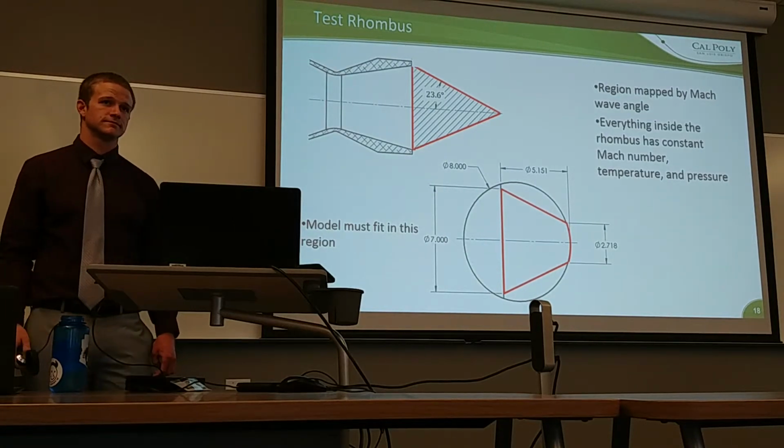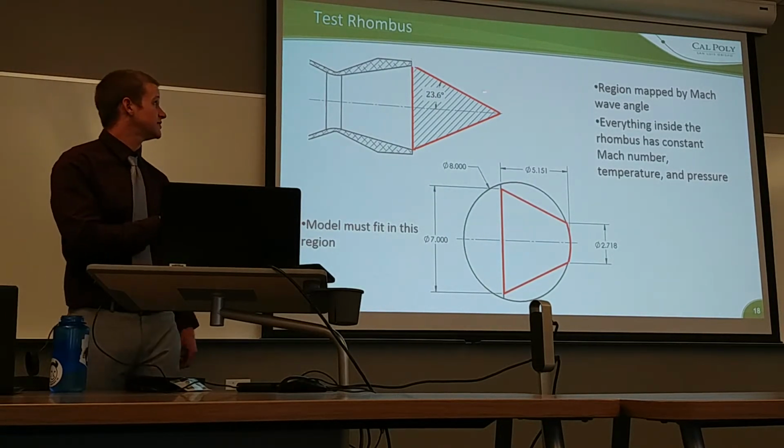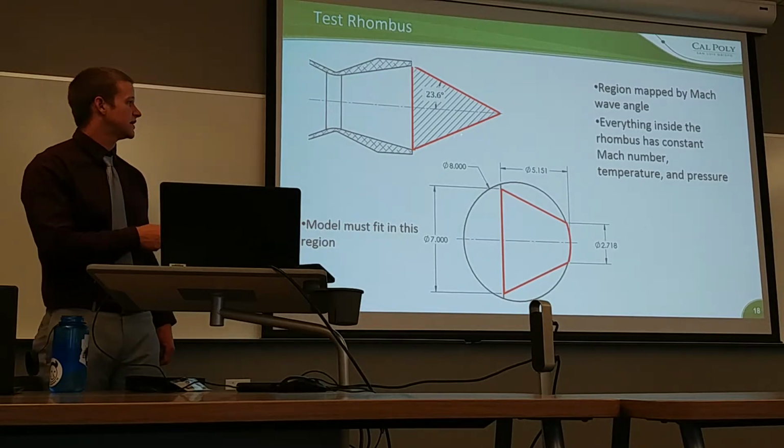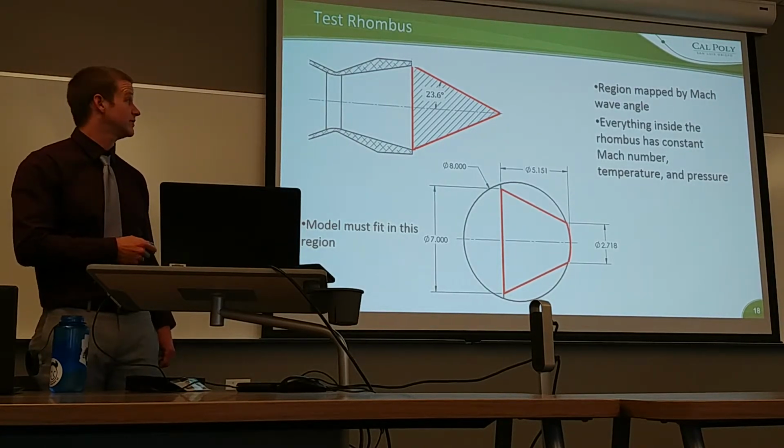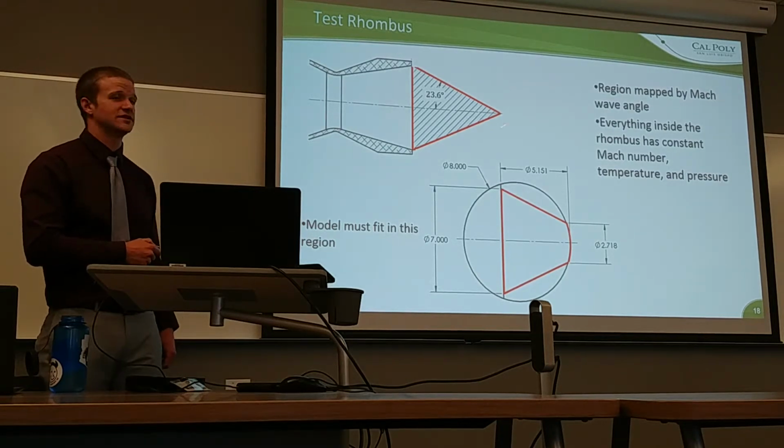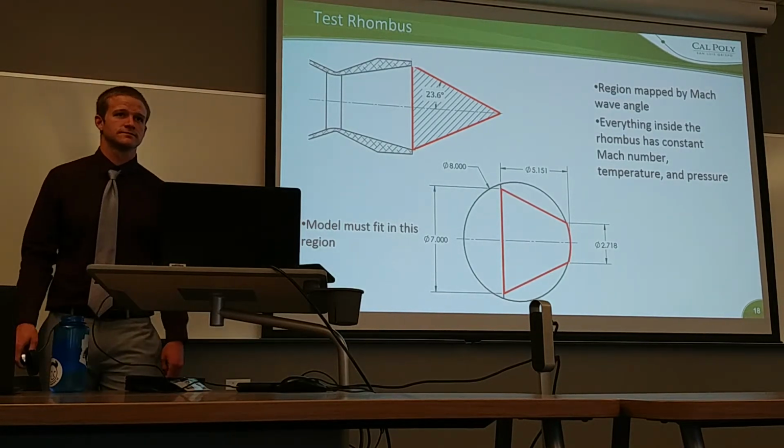It's just the flow is expanding and turning out into the chamber. Okay, so there's an acceleration. Yeah, it's accelerating. So everything out here is accelerated and is at a higher Mach number than what was at the exit of the nozzle. But everything that's inside is at the test condition. That's right. You said it was under expanded. Yep.